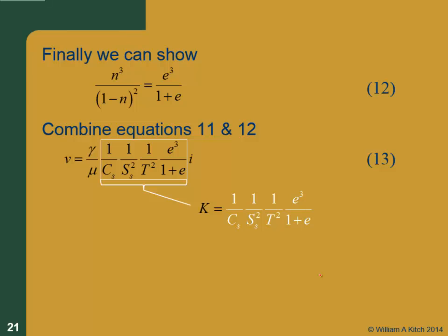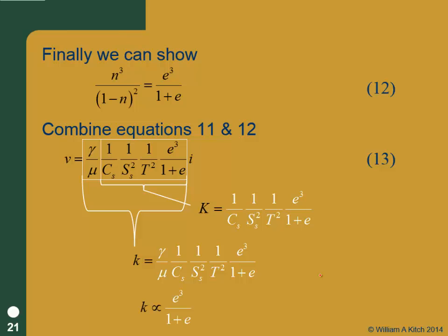All right. So notice that those four parameters there are the intrinsic permeability. Those are a function of only the porous media, right? Those are not a function of the fluid. But the whole thing is little k, or coefficient of hydraulic conductivity. We plug in gamma water, the density and the viscosity of water, and we're going to get K. But if there was something else flowing there, we could plug in other pore fluid properties.